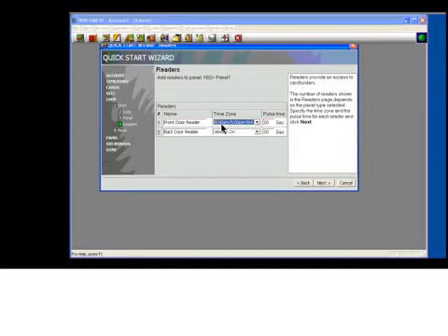Look at your time schedule up at the top, 8 a.m. to 5 p.m. Monday through Friday. That means that your door would unlock at 8 o'clock and relock at 5 o'clock. So if we put never on here, that means that this door will never automatically unlock. Now, what's the difference between the word none and the word never on? Both of them will keep the door locked 24 hours a day, 7 days a week. So you'll have to use your card to get in the door. Remember, we're talking about automation. However, the word none is nothing. There's no time schedule there. Where never on is a time schedule, but it's 0 o'clock to 0 o'clock. Basically, there's nothing in that block of time.